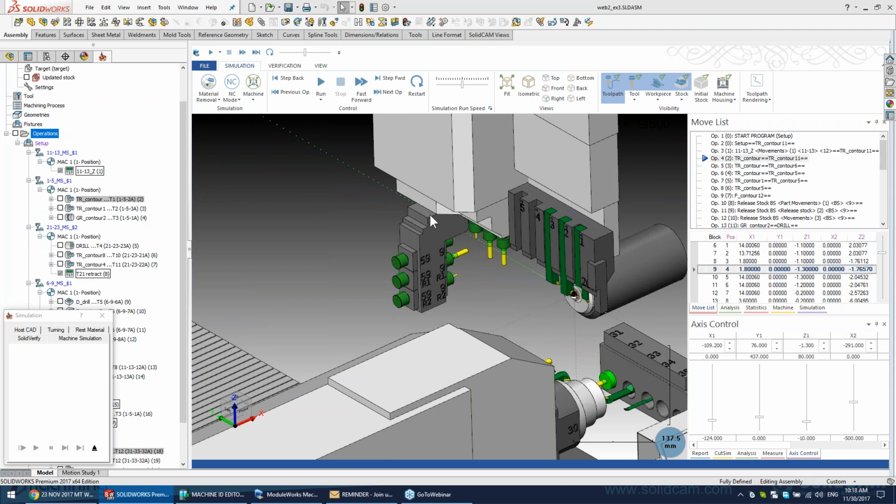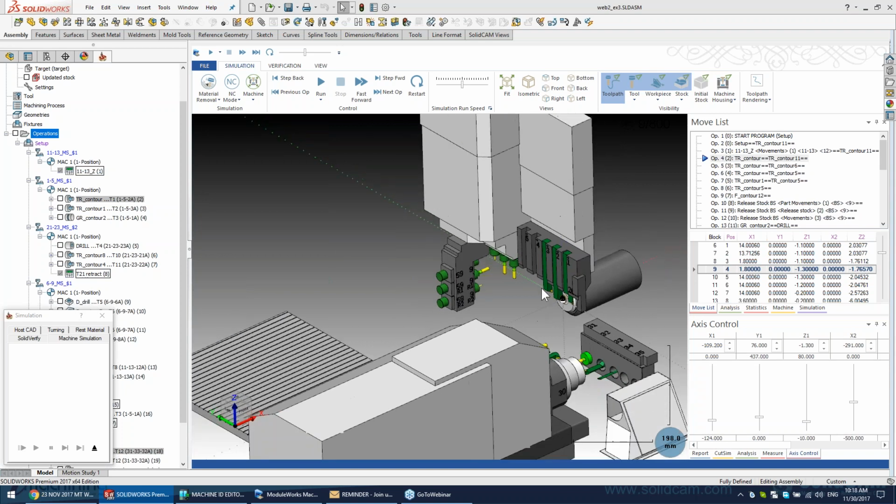Okay, so the user mounts this device in axial position, with the tools parallel to Z. Here at the start of the program, I'm having an MCO without G-code output, only for machine simulation, to position my device correctly, parallel to Z, in axial position. It's the MCO cycle that I create without a G-code output, just for simulation.